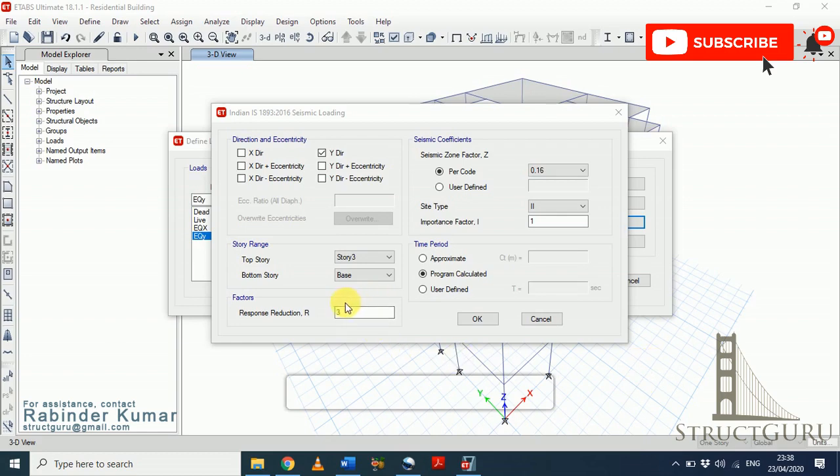this seismic coefficients. For example, if we are choosing response reduction factor 5 and the earthquake load is 1000 units in actual, this reduction factor reduces it to 1/5 of the actual value, and the building is designed to experience only 200 units of earthquake. Now the question is, why do we do so?